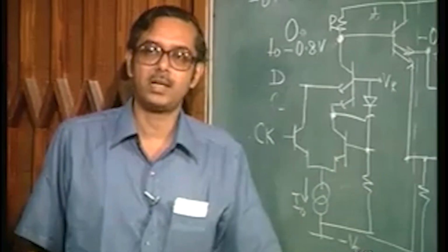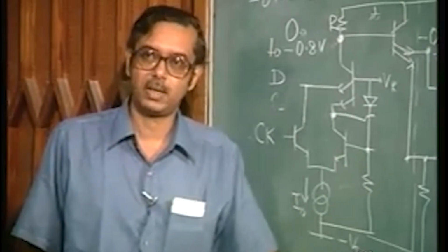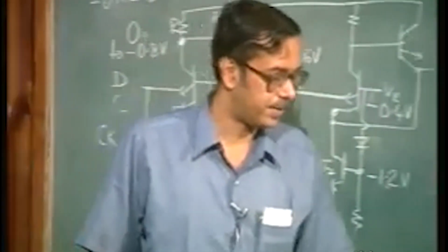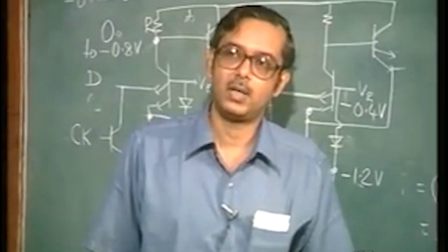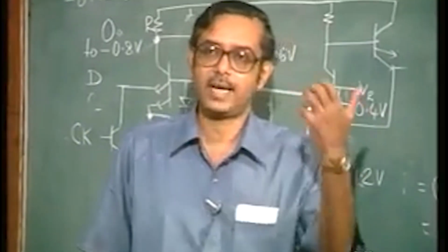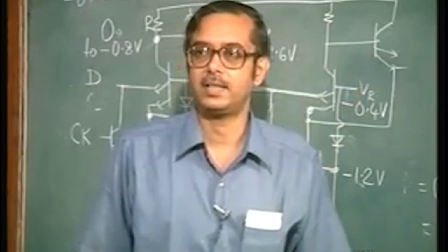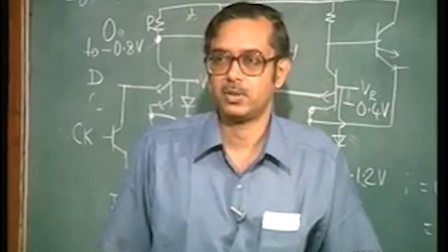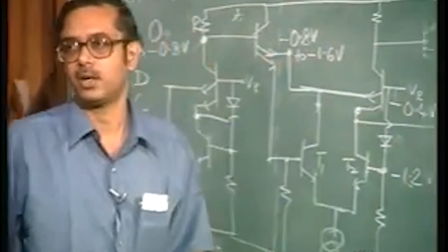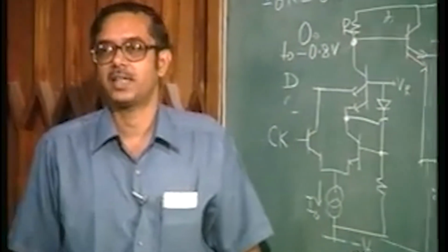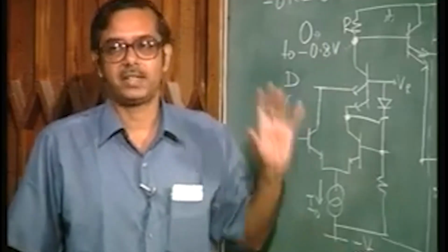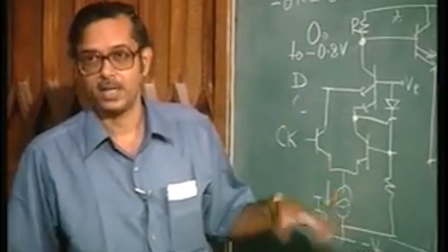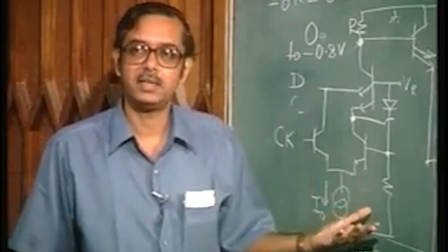See, if you reduce the power supply voltage, you automatically reduce power dissipation, and in today's world there has also been a drive to have lower and lower power dissipation, also because maybe you want a lot of handheld equipment which can operate with standard battery cells and so on and so forth. Maybe 1.5 volts people are talking of. All circuits should work with that voltage. Anyway, so there has been a drive to reduce the power supply voltage, which automatically means you reduce the power dissipation.